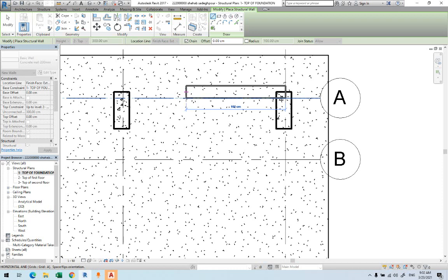I mean, you can set it to the exterior, or you can let it be interior. So you're just simply placing these things. Now you have two things: core interior and finish face interior. There is core, basically it's the structure. So the core interior, core exterior. Sometimes you have different layers, so you can even choose which layer to be on the grid line. Now for us here, I'll keep this one as a center line.